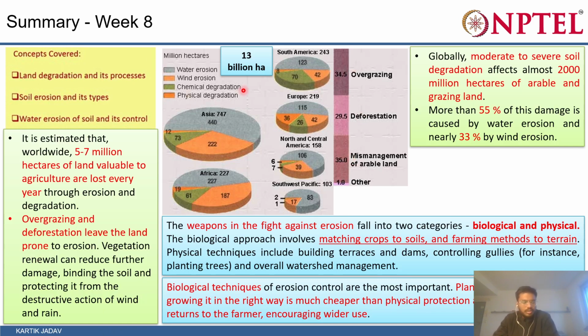So water erosion is the more prominent land degradation cause in any region of the world, and due to that, erosion removes soil as well as does not allow water to infiltrate. So considering this, if we have proper drainage conditions, that will help us. Due to that reason, it is very important. And other aspects are salt affected soil and water quality aspects.